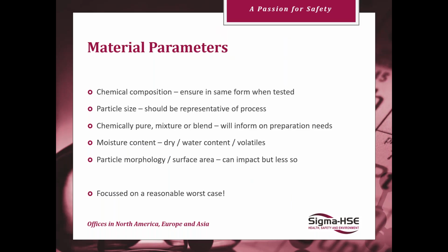Moisture content also is very important, and it's reasonable to consider a worst case where the material is in quite a dry state. When we're talking about fine powdered or dust materials, it's typically very easy for them to become dry around hot motors or exposed to sunlight and so on. So it's a very reasonable scenario to test it dry.